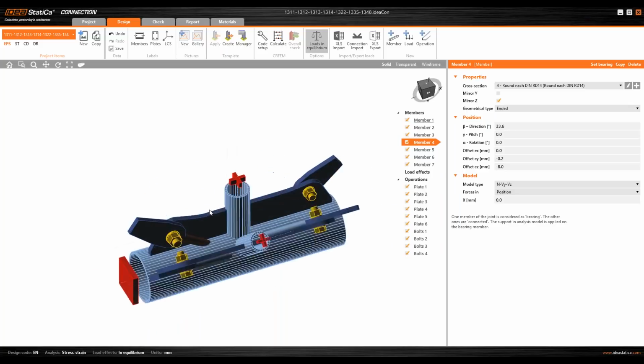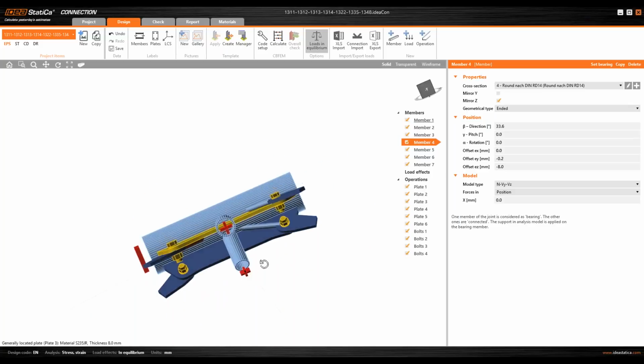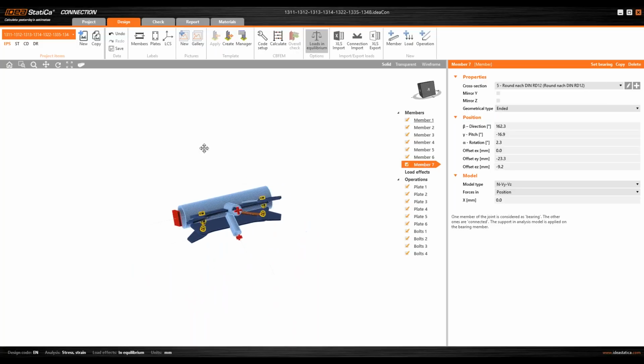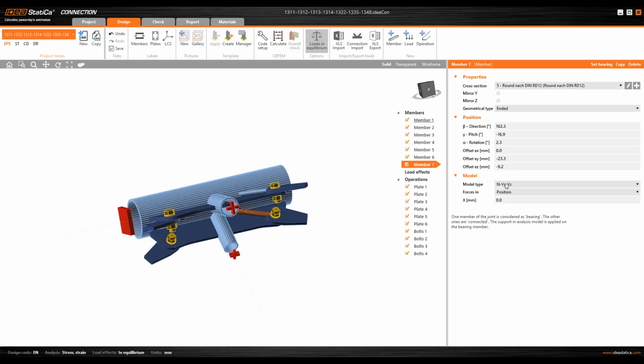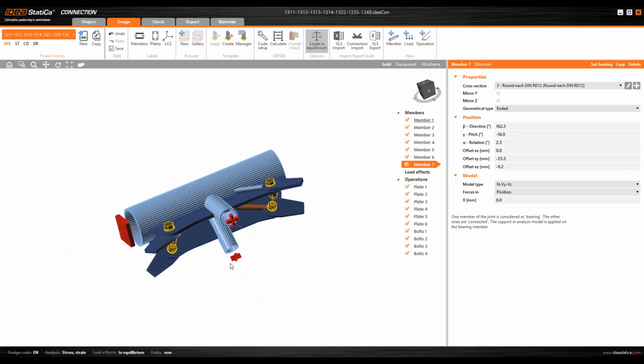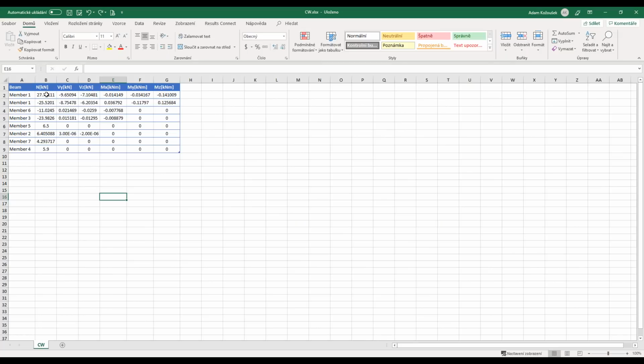Those are a bit hiding here below the gusset plates, but nevertheless, those are already set for the tension shear only. That's what we loaded from Advanced Steel. So those were actually well set, except that they are not connected. But we'll fix that.